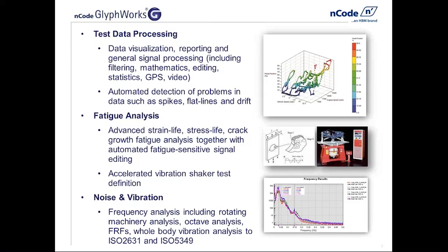GlyphWorks has a vast array of built-in fatigue analysis capabilities as well, such as stress life, strain life, and crack growth analysis. We can perform fatigue-sensitive time series editing to help accelerate lab or rig tests. We can perform fatigue analysis for entire proving ground schedules or complete flight spectra for the aerospace industry. We can also look at fatigue in the frequency domain and create accelerated vibration shaker profiles. Okay, we also have a variety of tools for noise and vibe analysis.